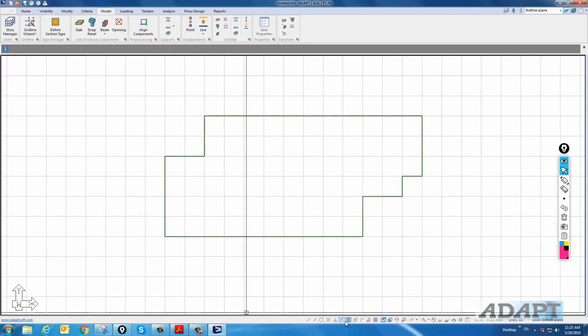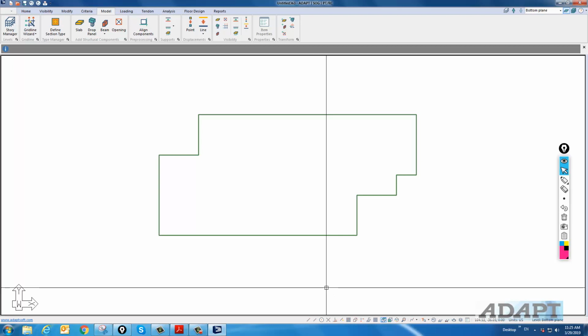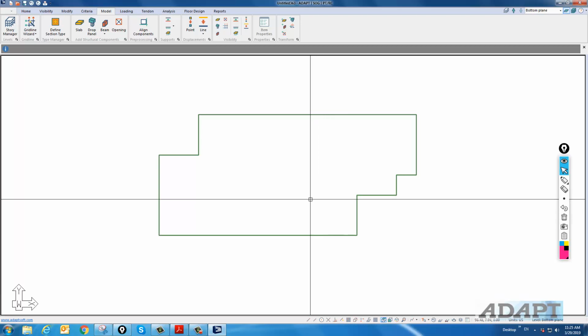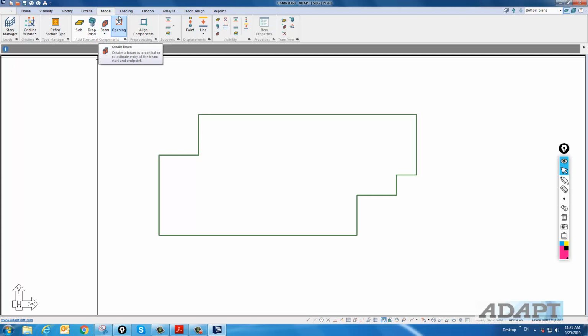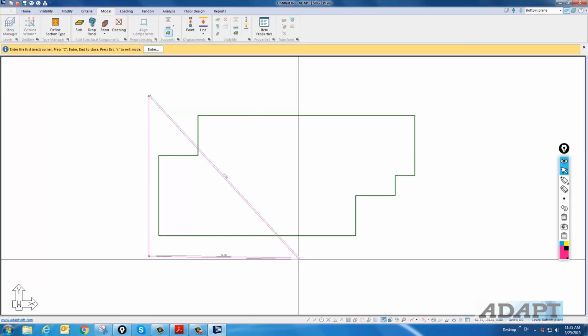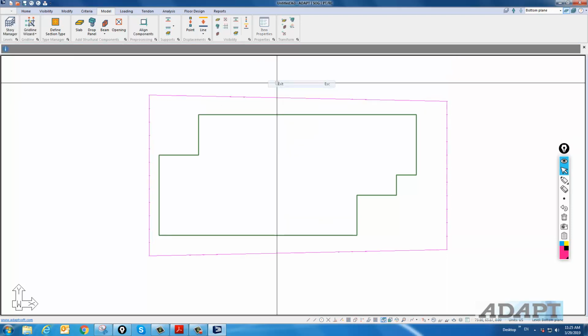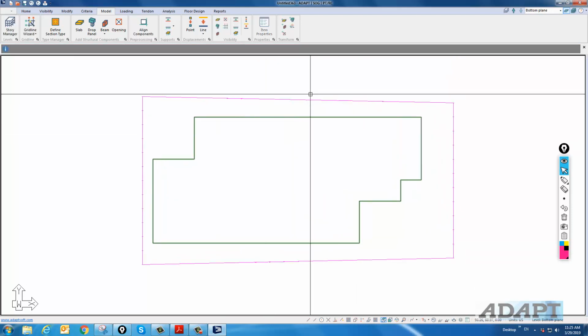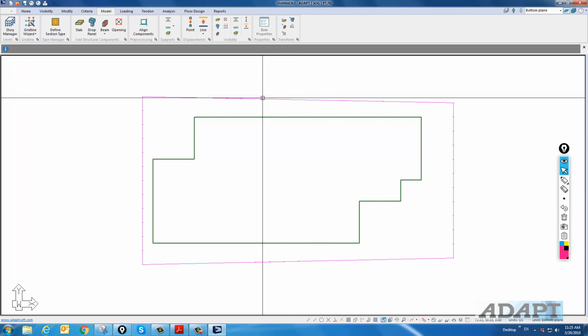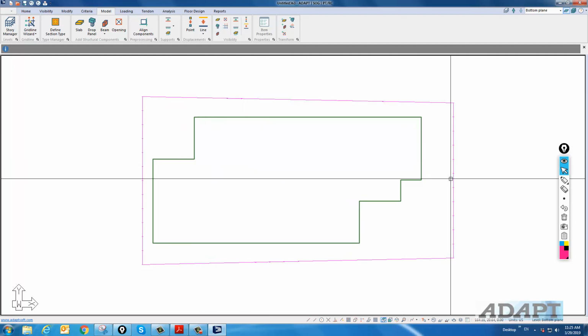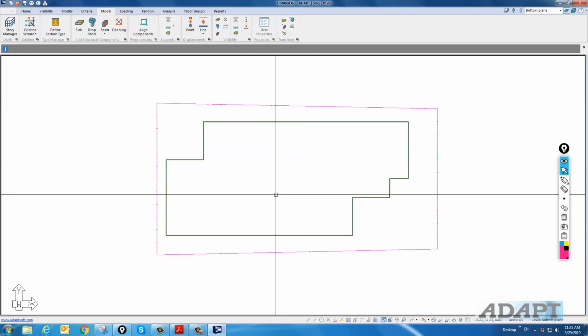Okay, the next step will be to create a soil support. So we'll go over to, again, modeling. We're going to select the option for supports, and we're going to select an area spring. And this can be placed around the slab like so. Okay, we're going to go back and adjust this after we model and just check the model for validation. We'll go back and adjust this for the center lift condition, but for now we'll leave it in this position.